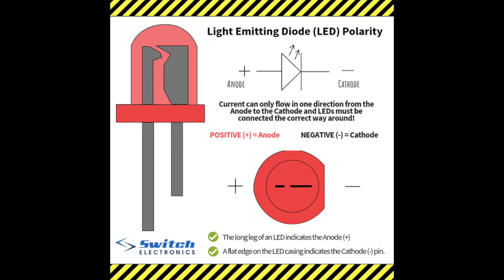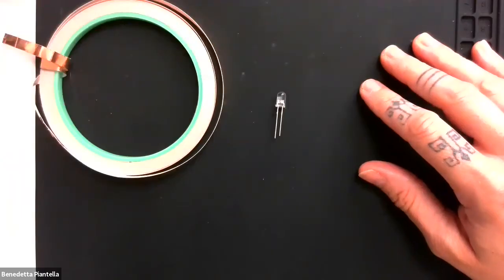The reason why I'm mentioning this is because sometimes when you prototype a paper circuit, you forget and things don't light up or don't work. And so one first thing to troubleshoot or check is if you actually had your component situated in the correct orientation.